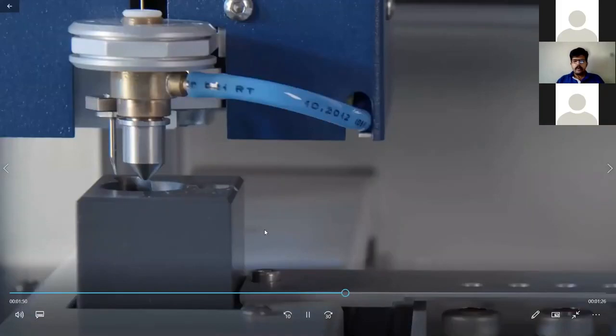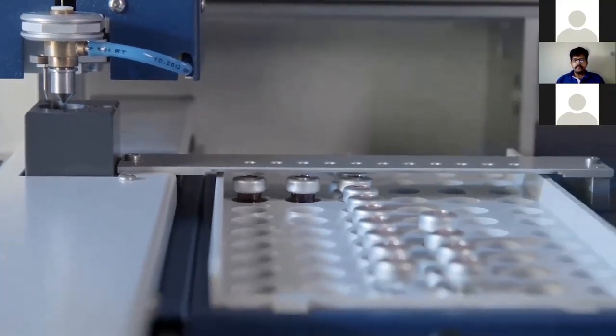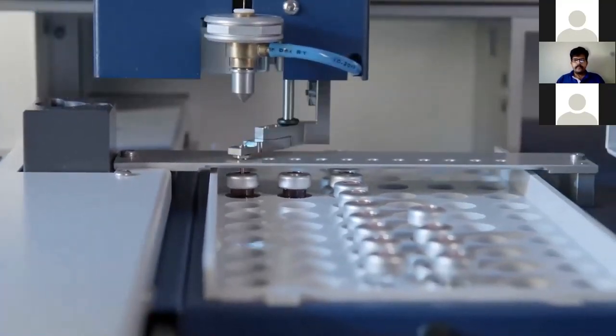So this is how the application process works. The sequence starts by rinsing the syringe. Next, the syringe fill-up happens. The septum is punched and the needle lowered into the sample vial, thus allowing the syringe to be filled with the sample solution. The septum punch is retracted prior to the needle being removed to ensure the outside of the needle is wiped off by the tightly closing septum.